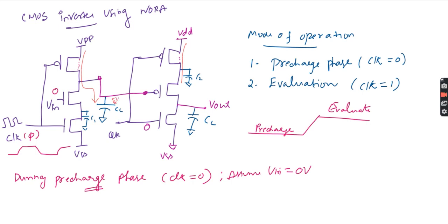If it is 5 volt, the PMOS has 5 volt, so the PMOS is off. So the VDD will be charged, and I will get the output here. Now it's not evaluating. When I give the input equal to 0, I am not getting anything as of now. So at that time, what will be your output? You may think, here I pre-charged, but what about this stage? You will have the question about this stage, correct?